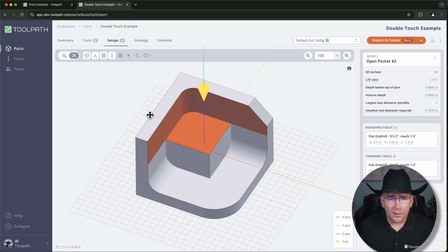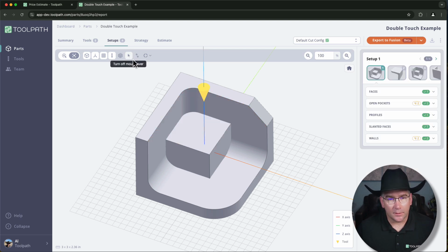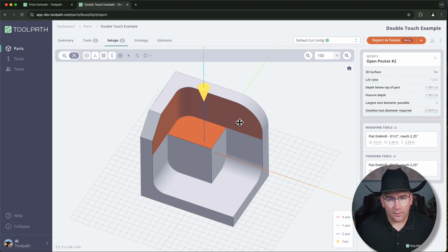Now there are some showstoppers too that cause some issues in identifying parts as being unmachinable. And in this case, we can see an area where to machine this flat surface, a machinist knows they would extend past that surface. And while the way we've been training the system was to minimize the amount of tool changes, minimize the amount of runtime, minimize the number of setups, in the past, it would avoid machining the same surface twice, but there's an overlapping area when you machine that's naturally going to have to be machined twice. So if I select this other area, these corner spots need to be machined twice.